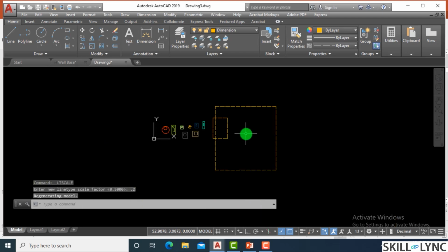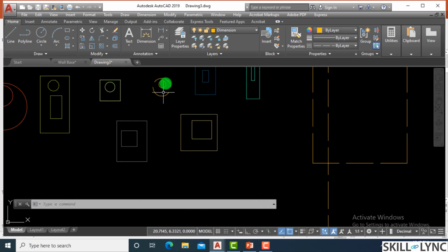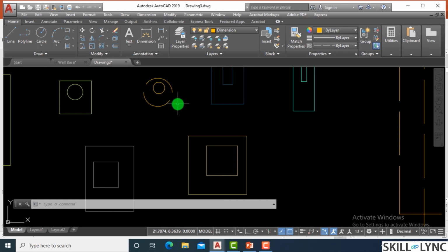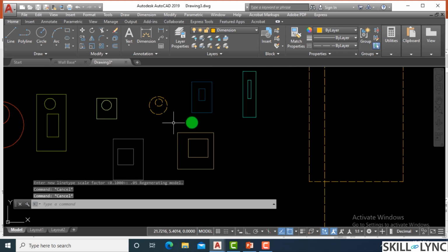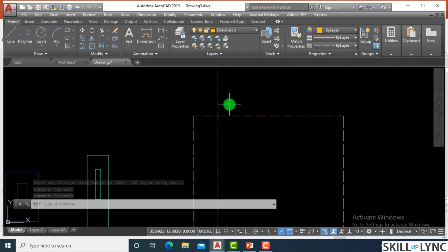I wanted to show you how line type and color combine. Now this particular circle is showing the line type. Let me scale it to an extent, let's say 0.1, 0.05. Now it is shown correctly. How do you select a line type scale? That is a very important part, but let's come back to the point.